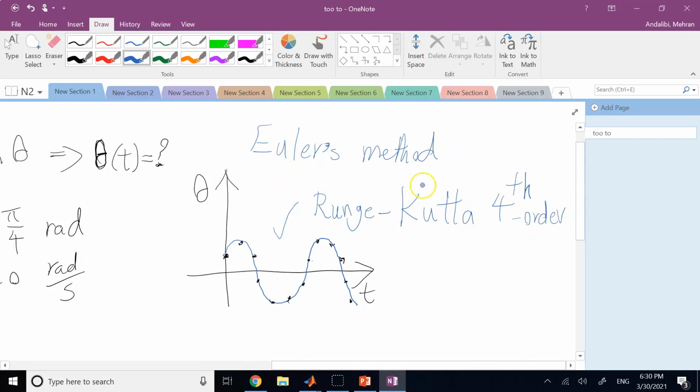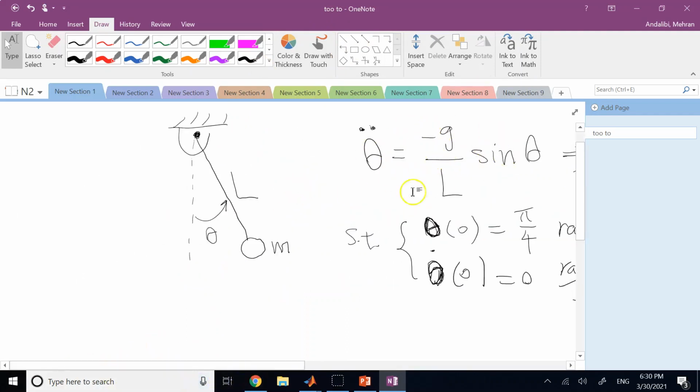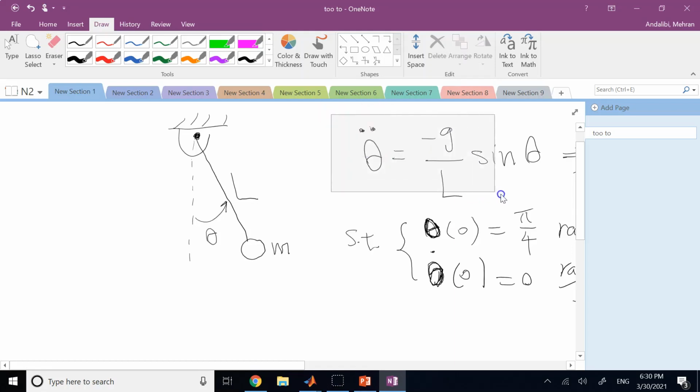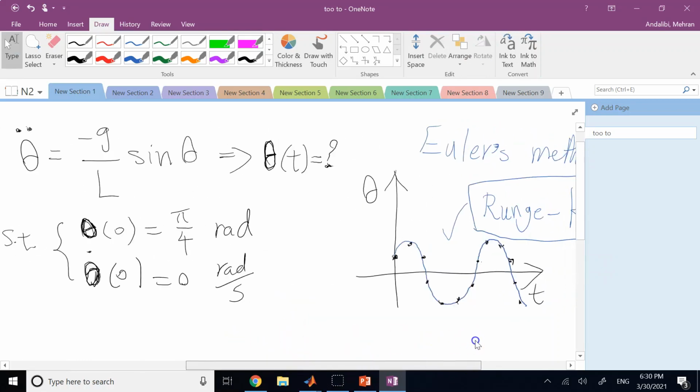Which is more accurate than this guy. So this is what Simulink and the command ODE45 in MATLAB are using for the category of differential equations we call non-stiff. So here, if we want to do it in MATLAB using Simulink, not ODE45, what we need to do is to create some blocks and basically recreate this equation using blocks, implement these initial conditions, and then let Simulink solve it, and then we can look at the solution in an oscilloscope block.